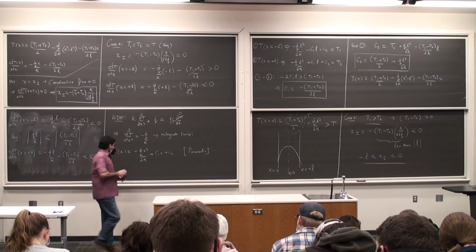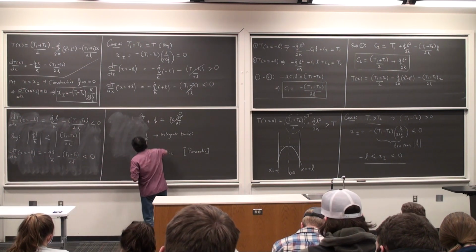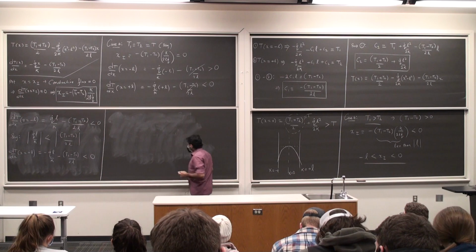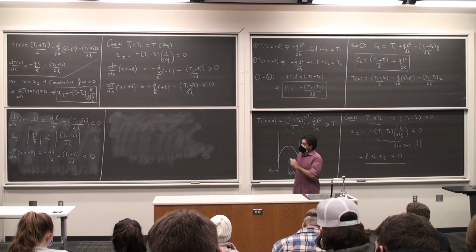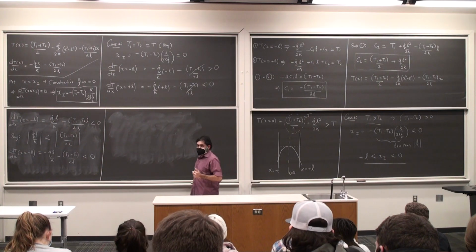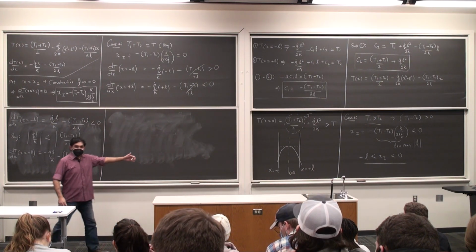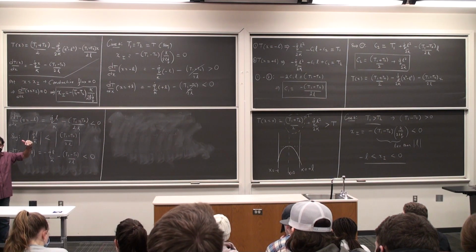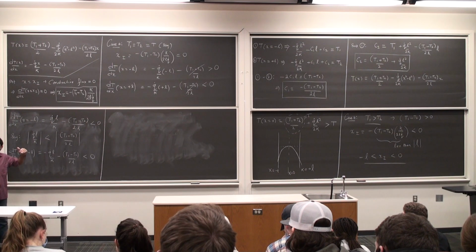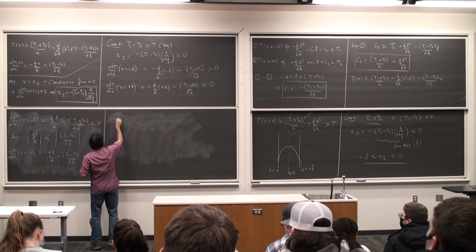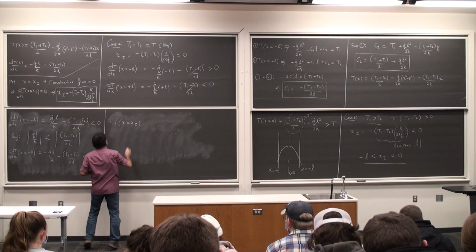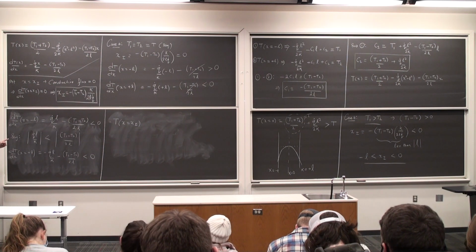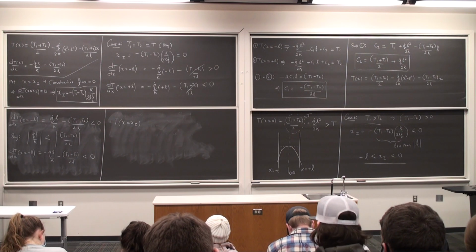So now I am in this very interesting situation in life where I have the following. I have a negative slope at the left side of the wall. I have a negative slope at the right side of the wall. I have a 0 slope at x is equal to xi. If I calculate the temperature at x is equal to xi, if this temperature is going to be less than T2 and less than T1, then I am actually okay.